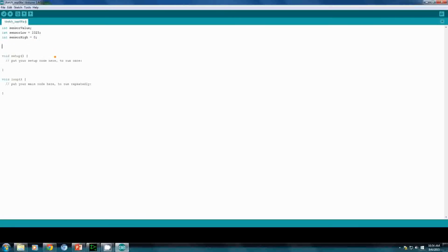So now let's create a constant, and it's an integer type, and we do LED pin. Okay, so now notice that in our circuit and the components that we're using, we didn't have an LED as one of our components. The reason being is that there is already an LED attached to the Arduino board, and internally, the way this Arduino board is set up or built, it is connected to pin 13.